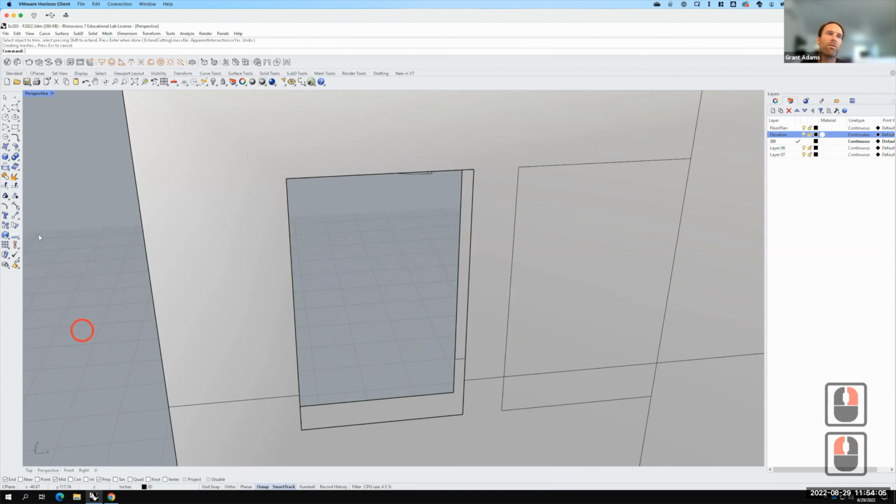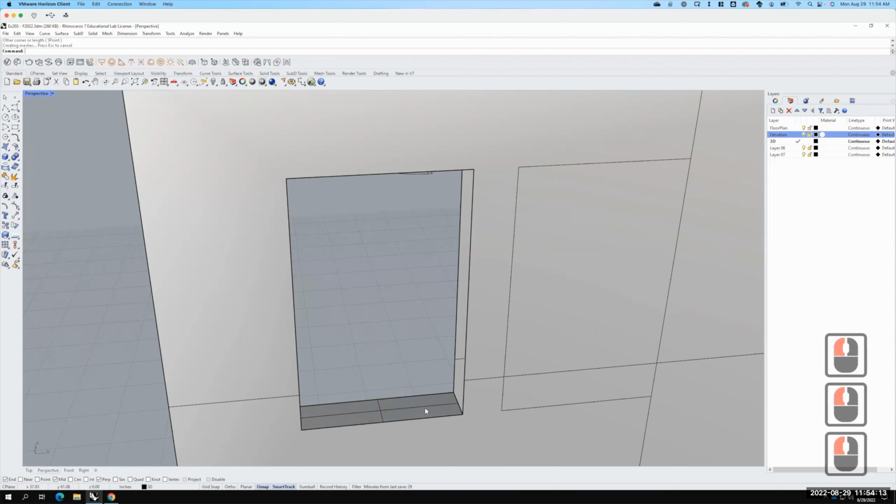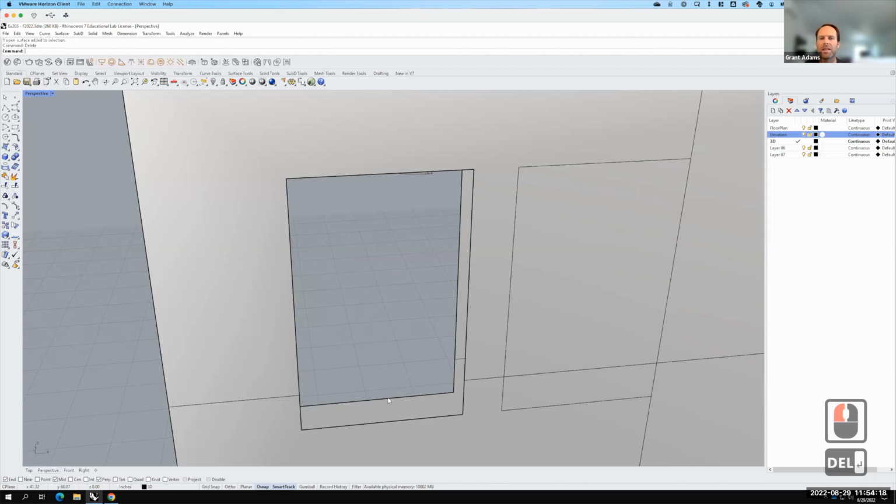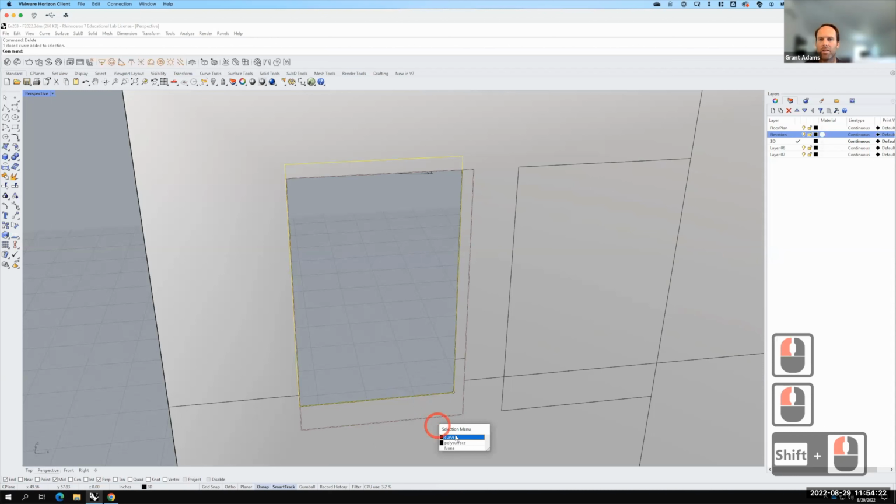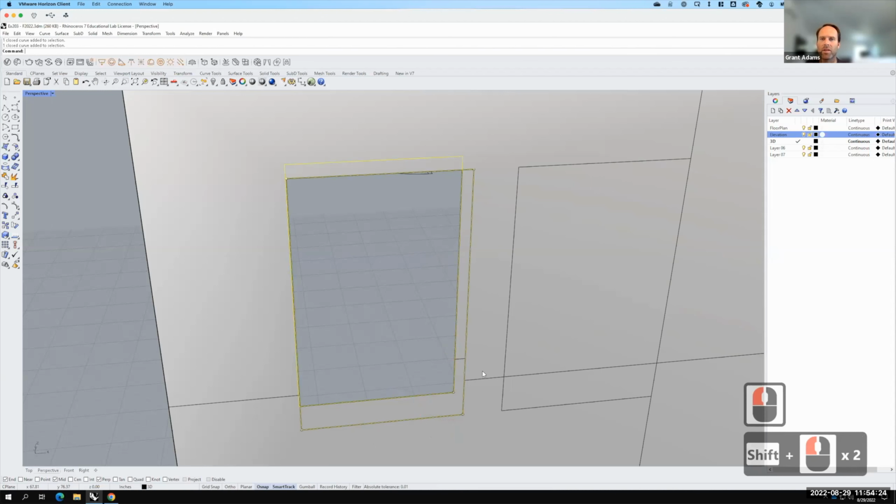So we've done this before. I could come back up into my surfaces, and I could create rectangular planes, and I could fill in these inside surfaces. Now to me, that's a lot of work. So rather than do them individually, I might take this curve that I created and this curve here that I created, so the one on the inside and the one on the outside, and then let's use a loft instead.